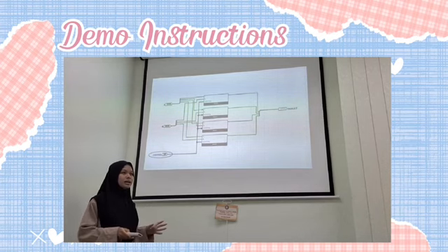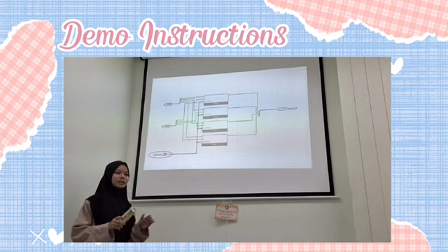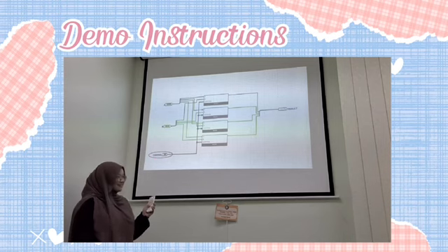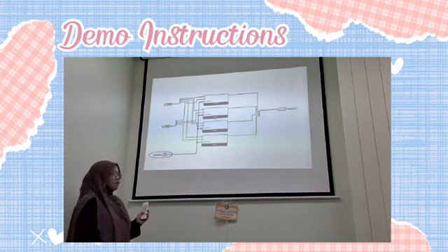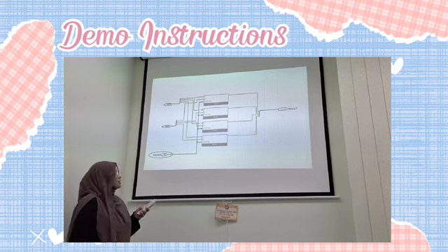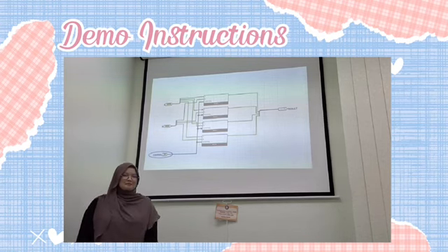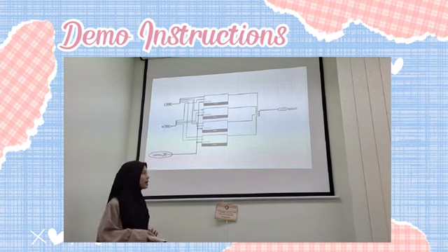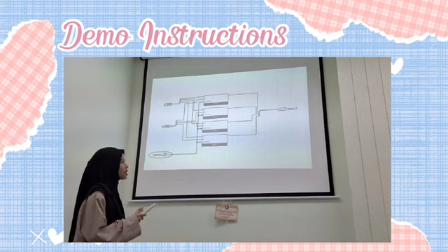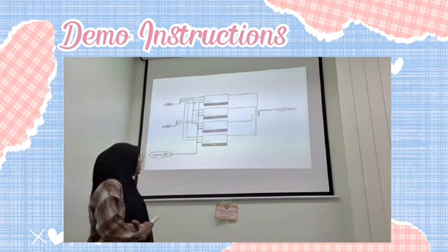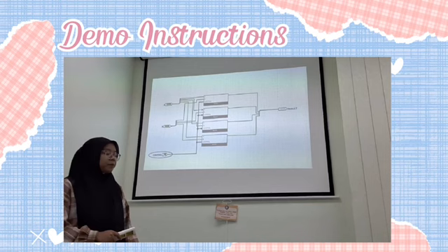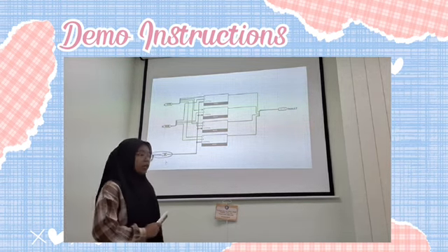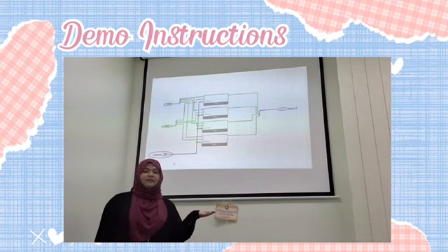This is correct because for the AND operation, 1 and 0 is 0. Next, we will change the selector to 01 for OR. So the output will display 1110. After that, we change the selector to 10 for the XOR operation. As you can see, the result is 0110. Finally, let us test NOT A by changing the selector to 11. The output will become the inverse of A. As you can see, the simulation ran perfectly without error.